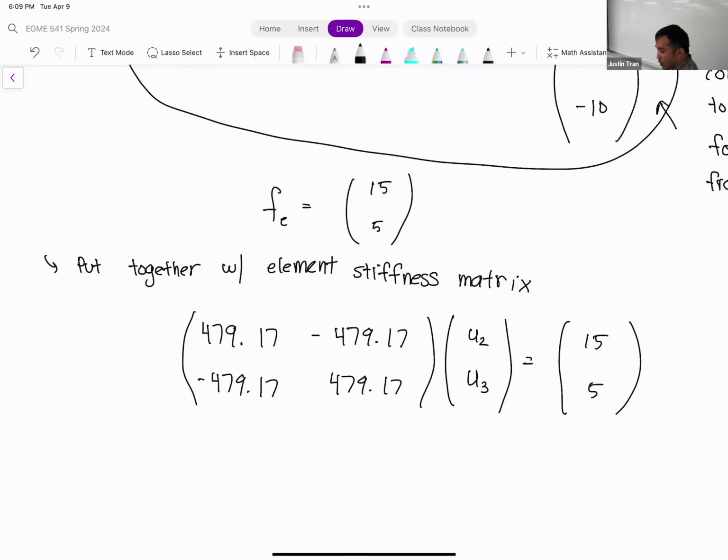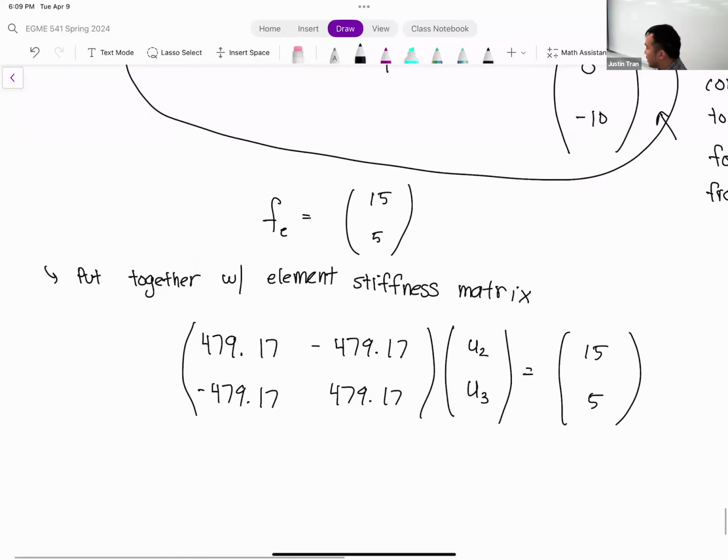All right, so now that we're done with the elemental systems, from here it's pretty straightforward. The biggest difference between what we're doing now compared to the direct stiffness method is how we form these element stiffness matrices and element forcing vectors. In the direct stiffness method, we kind of shortcut this where I just gave you formulas to plug into. Granted, they were extremely tedious formulas, but they were kind of plug and chug. With these kinds of problems, there's a little bit more work involved. You actually have to perform some integrals, and sometimes multiple integrals per element. But from here on out, it's the same thing.